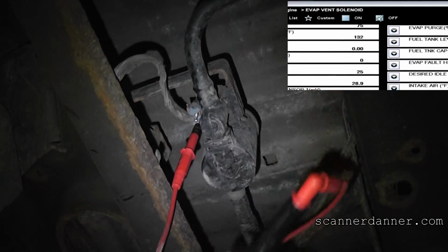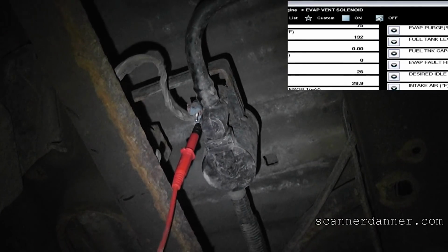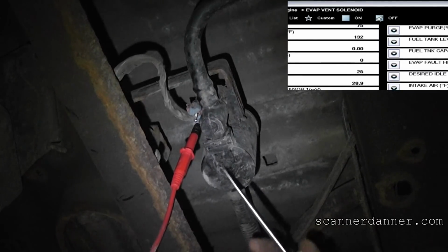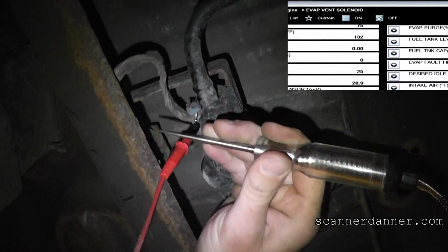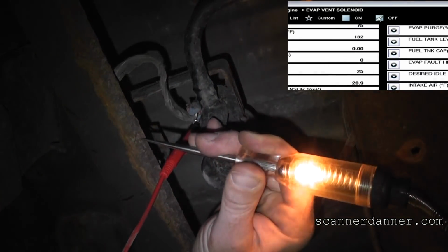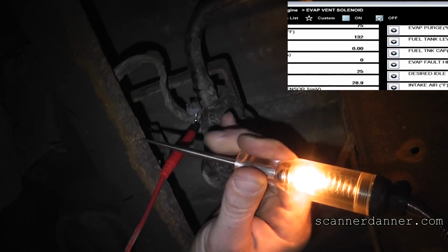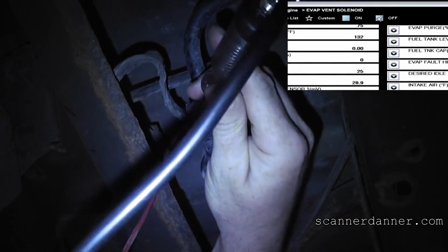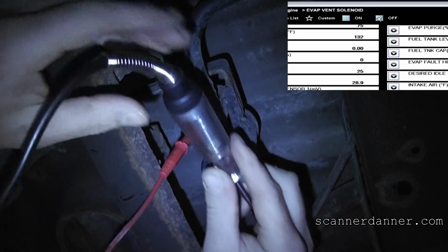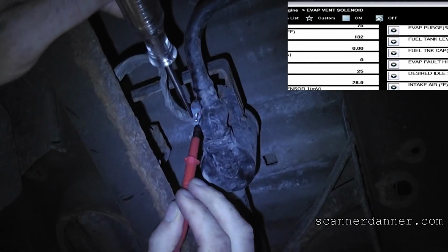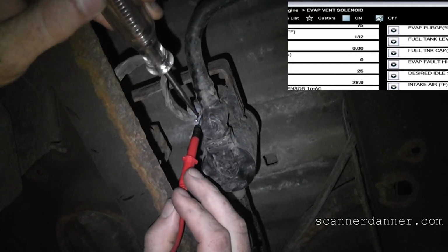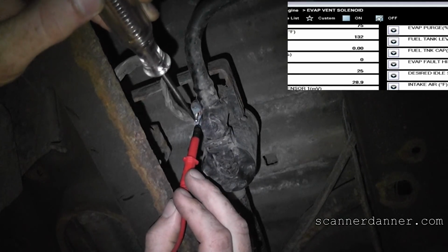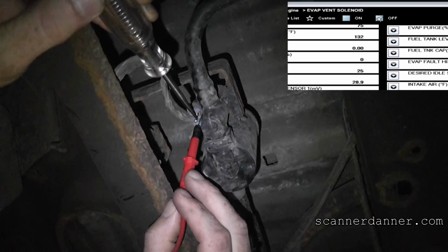Yeah. Okay, so does my test light have battery positive on it right now? If I touch a ground, which is a very rusty ground, see my light? What do we want to see on the solenoid control wire when Bell turns the driver on? Hold on, let me touch the pin. Being extra careful that these two pins do not touch each other. Go ahead.